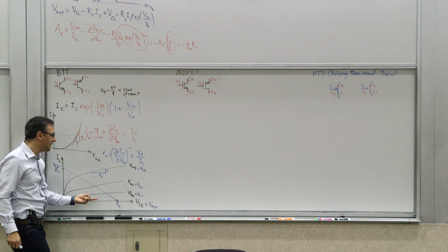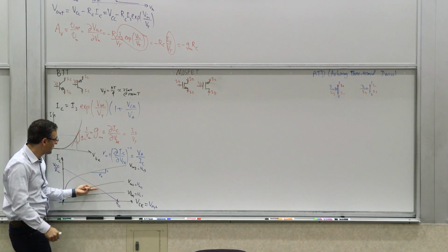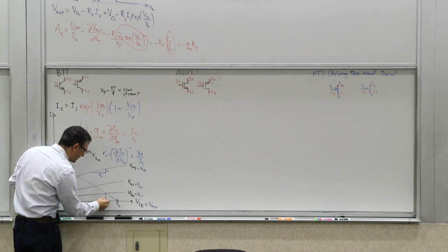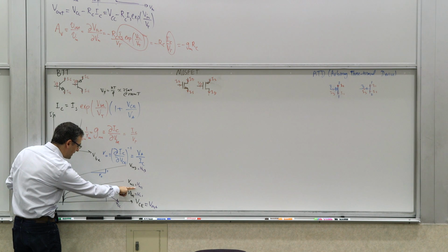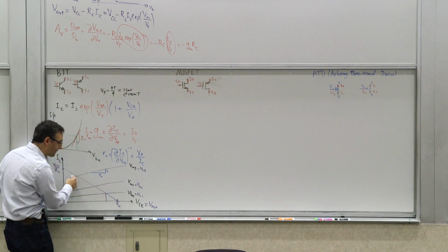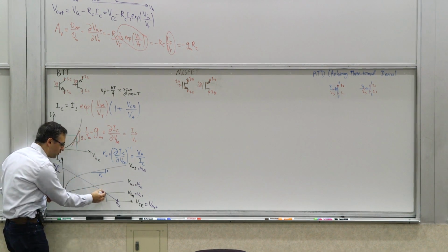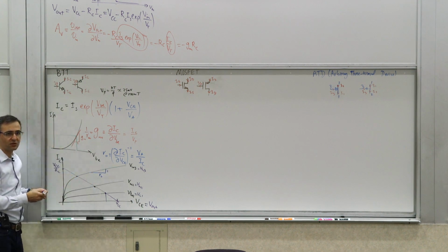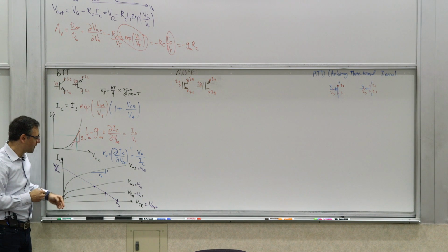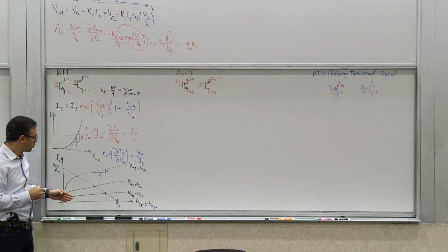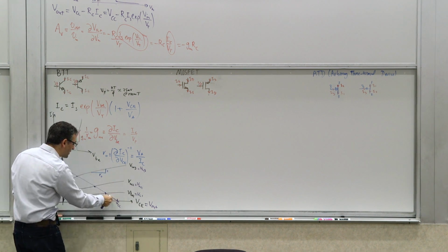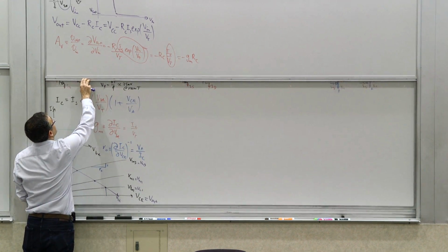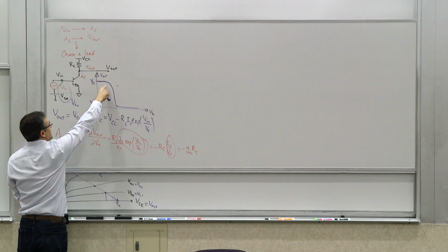As you increase V in, your operation point, your V out, which is this point on the x-axis, moves from right to left, because the operation point is the intercept point of the appropriate black curve, which is the transistor characteristic, and the purple one, right? So as you increase V in, this voltage starts dropping, which is exactly this behavior.